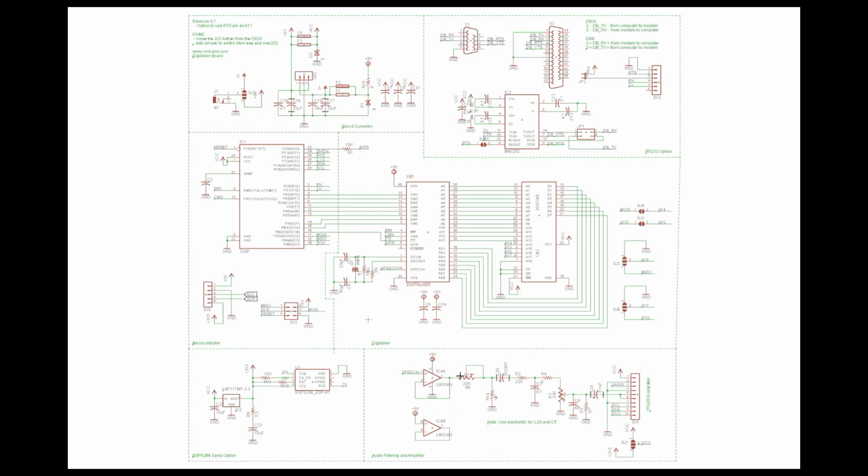So we come out of the op-amp, we go through a resistor and capacitor. That is our filter. This here is a 0 ohm resistor, and then we go into this pot, which is our volume control. Now you notice there's some components here marked no populate there and there, a 0 ohm resistor here, no populate resistor there.